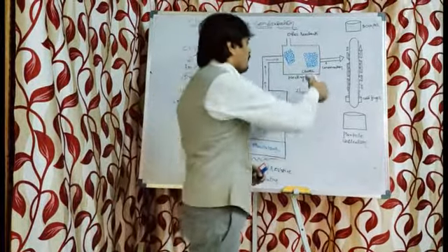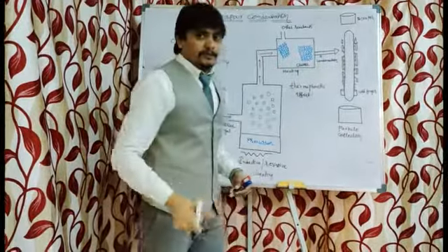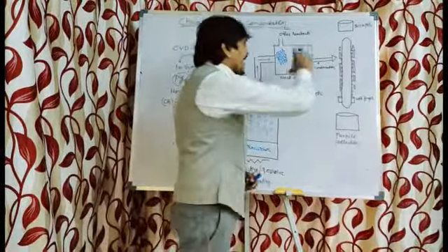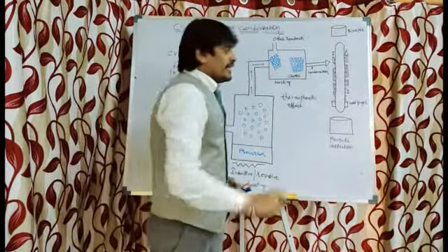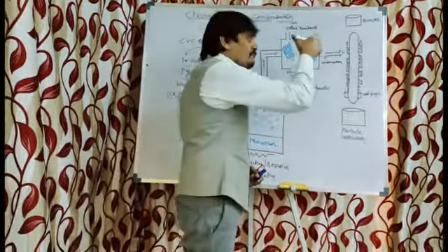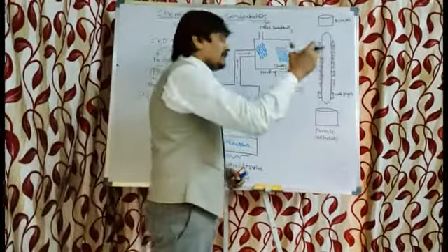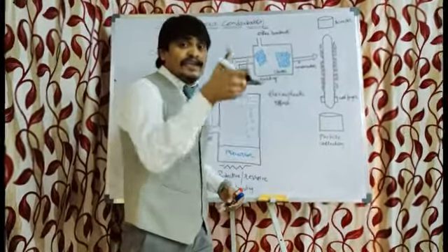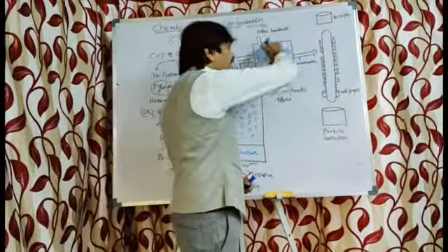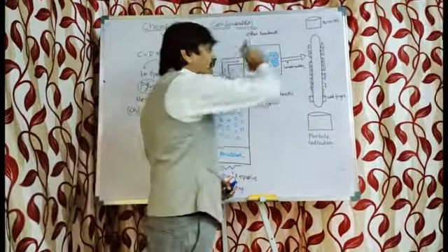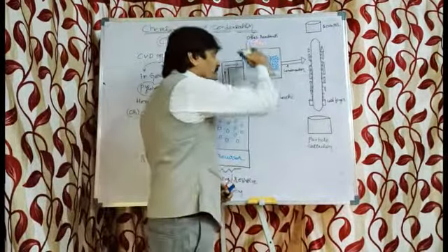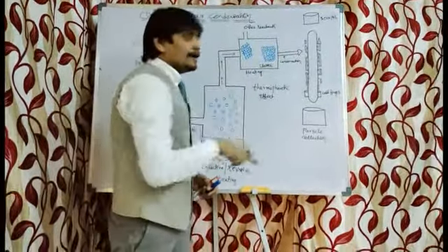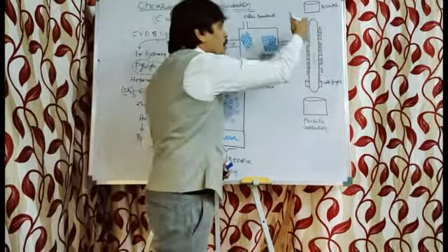Now because of this thermophoretic effect, whatever nanomaterials have been formed, either metal nanomaterials or ceramic nanomaterials, which are very hot and adhering or sticking to the hot chamber, will repel from the hot surface and be attracted towards the cold surface.